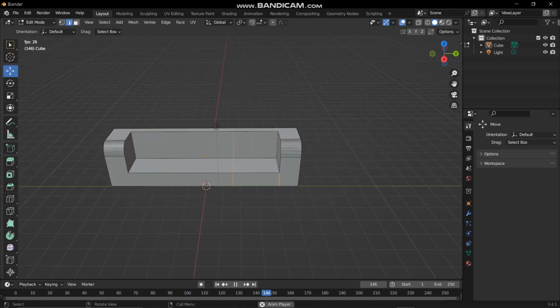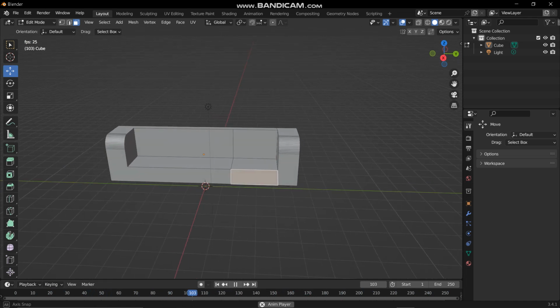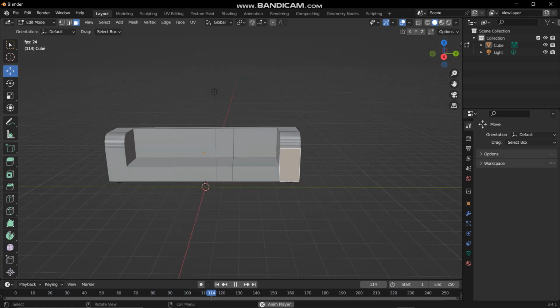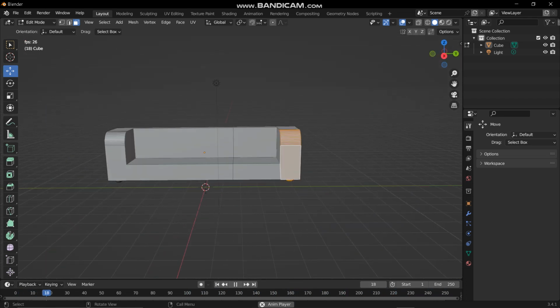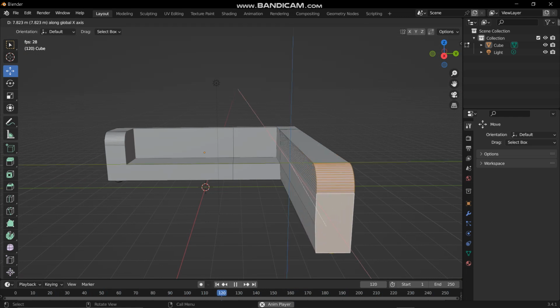And now I can just do this. Once I select a face here, I go into the face view, and I can select the number of faces that I want. Using the extrude tool, which you can see over here, or if you press the shortcut key E, you can highlight. So I want to highlight this face as well as this area that we just did. I'm going to hit my E key and pull forward like this.